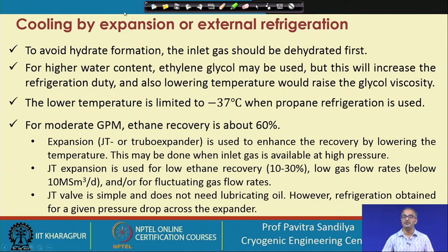it is seen that we dehydrate the gas before we go for the NGL, and now we can understand the importance of dehydration in the natural gas processing and why we need to maintain the particular sequence that we have: to first dehydrate the natural gas before we take it for any further processing. So, this is why any kind of hydrate formation will be avoided if we are taking out the water initially.